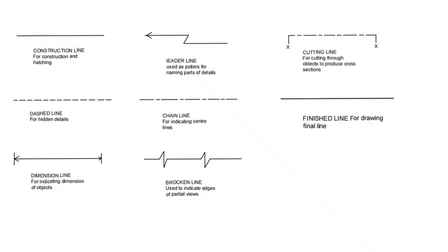Then the broken line is also called continuity line. This line helps us in breaking drawings that would otherwise not fit in a drawing paper. So we cut that drawing and show that the drawing is still continuing even as we cut it because of the space.